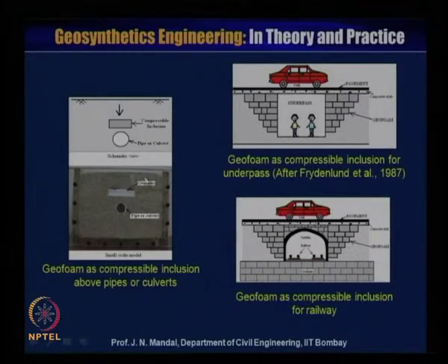Alternatively, if we provide the geofoam material either in semicircular form or in rectangular form, then because of its compressible inclusion, stress cannot be distributed to the pipe, and the pipe will also be safe due to the application of the load.